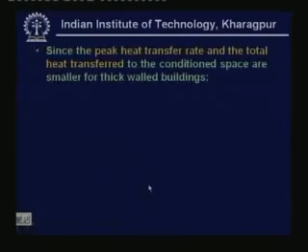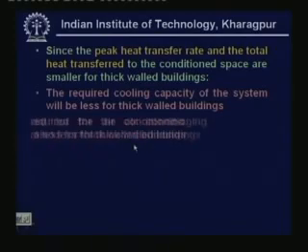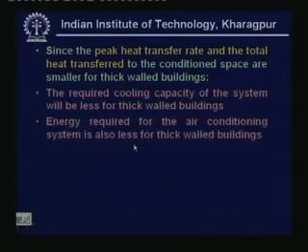So since the peak heat transfer rate and the total heat transfer to the conditioned space are smaller for thick walled buildings, the required cooling capacity of the system will be less for thick walled buildings, so it is an advantage. And energy required for the air conditioning system is also less for thick walled buildings. So this is also an advantage.